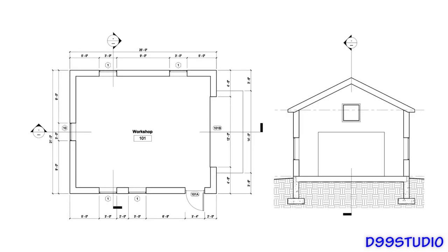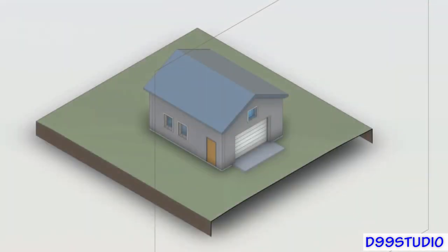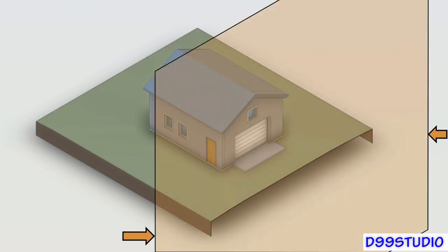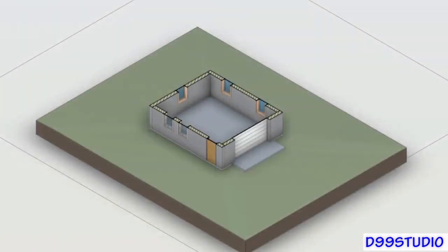Consider standard drawing types like plans, sections, and elevations. How does Revit generate these views? Well, it starts with a cut of the model. In elevation, this would be a vertical cut, usually outside of the building and facing toward the model. For a section, it would be similar, except that this time the cut slices through the model, thereby excluding elements that fall behind the cut. The most dramatic example is a plan. Here, the cut is horizontally oriented, showing only a thin slice of the model.